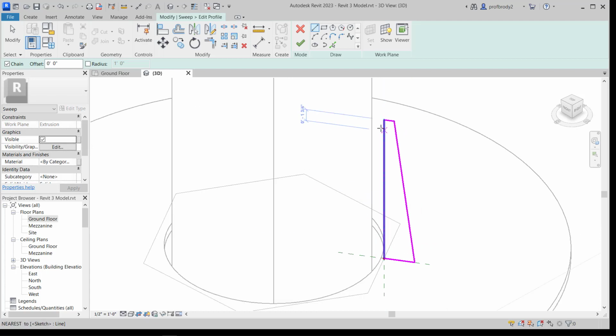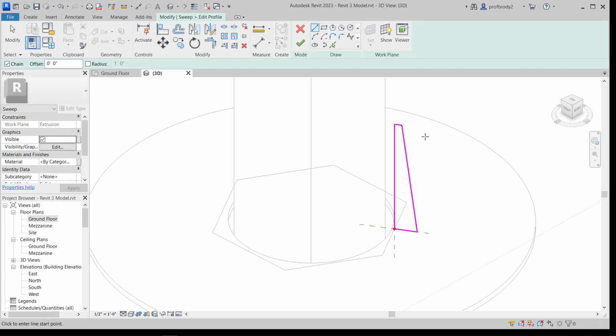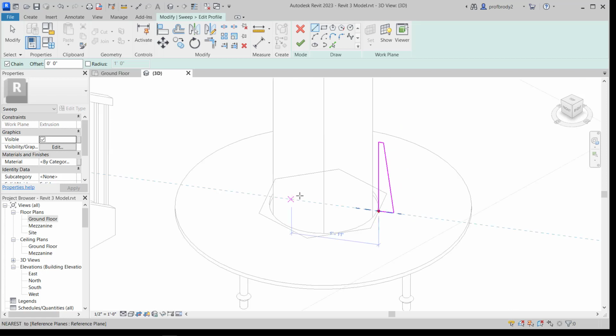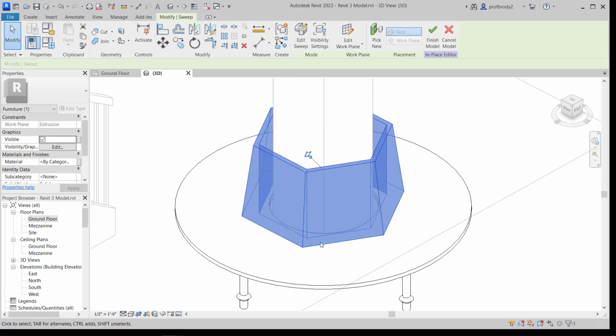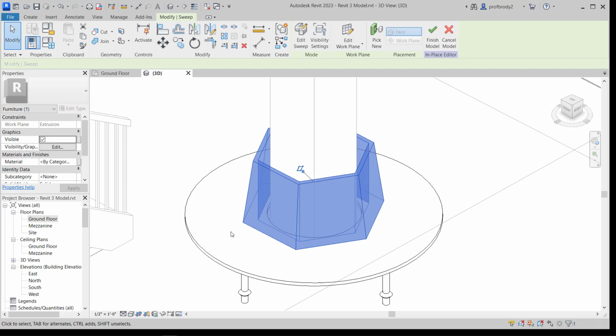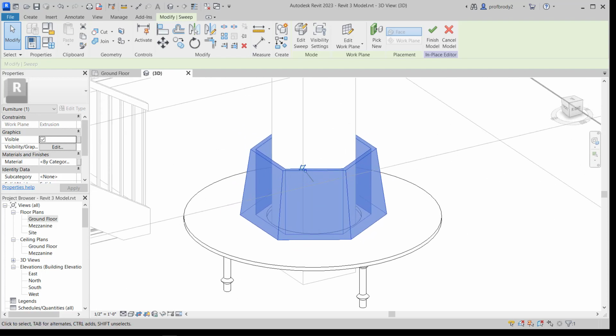We'll give it a little kind of bevel that goes up a certain amount. Go. And of course, you can add in little hooks and curves to make your design fun and interesting, but we don't want any fun and interesting. So now I'll exit the profile sketch mode. Now I'm back in the sweep edit mode. Here's my path, here's my profile, and then you just click the finish edit mode, and there you go. You've got yourself a nice back for your model.